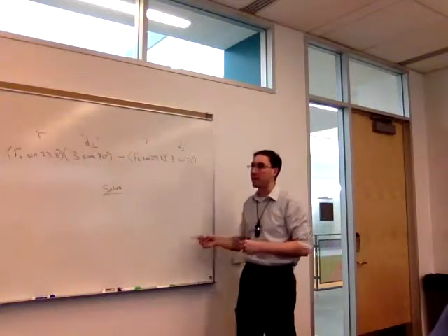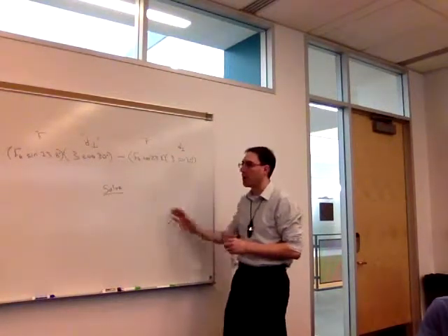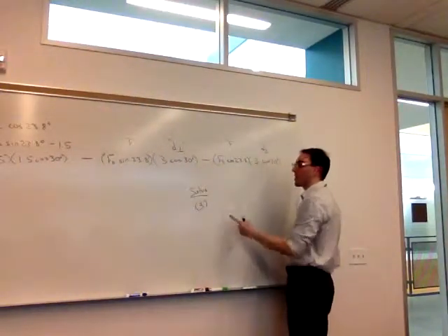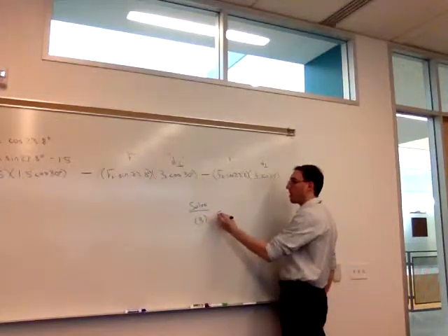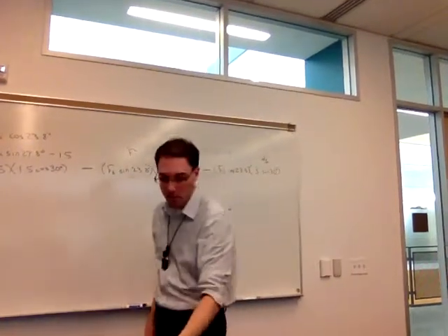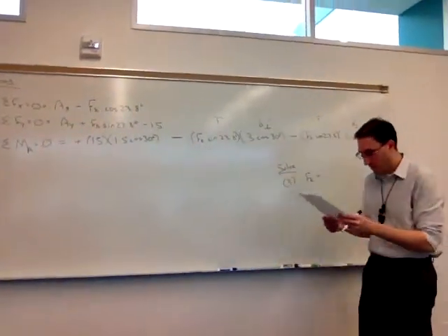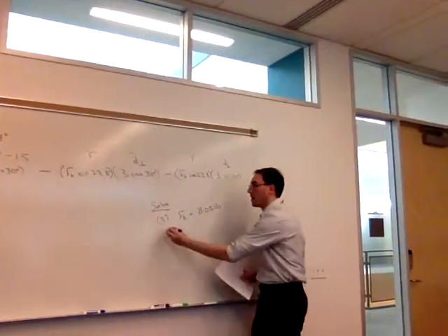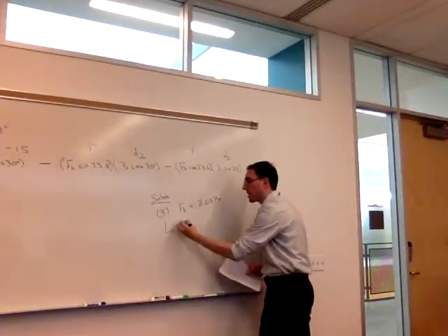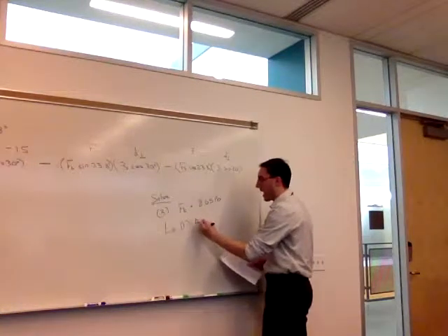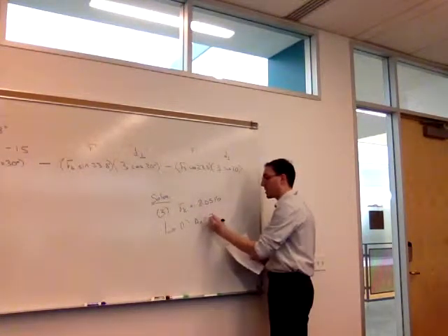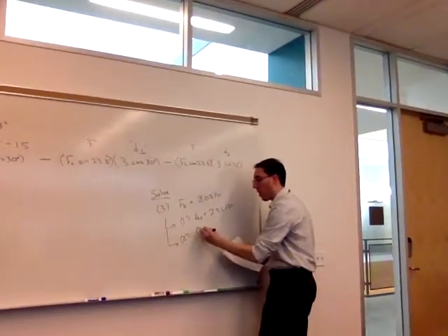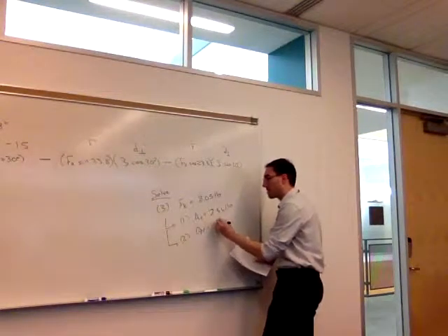So I would say if we're doing it by hand, we probably want to start solving as soon as possible, but we can go back and write more equations. So based on equation 3, because we picked that point A to take the moment about, we can easily find the force in the spring is 8.05 pounds. And because we have equations 1 and 2, we can put that result into 1 and get Ax is 7.36 pounds. And we can put that into equation 2 and get that Ay is 11.8 pounds.